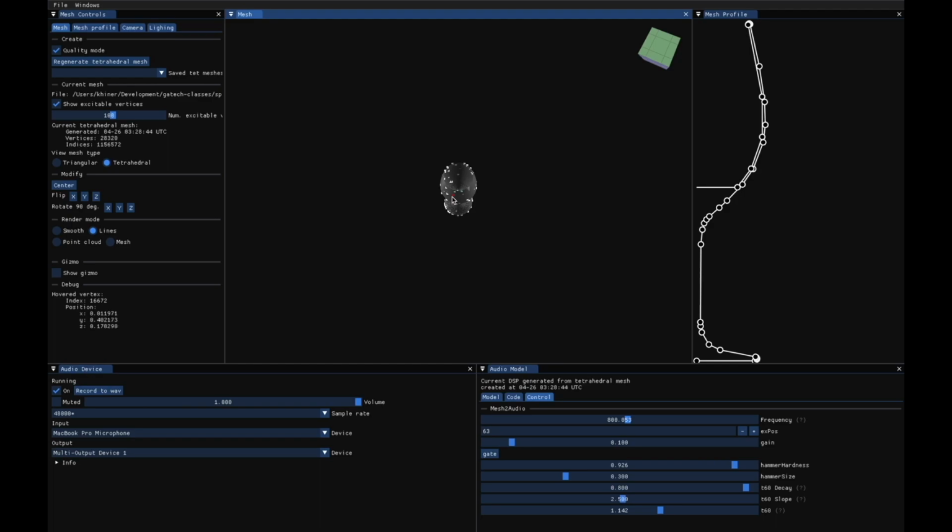Since calculating a 3D model can be computationally expensive, for our project we also investigated estimating a 3D audio model by carrying out an axisymmetric finite element analysis directly on a 2D profile. This avoids a ton of compute time by skipping tetrahedral mesh generation entirely, as well as making the finite element analysis and eigenvalue estimation much faster.